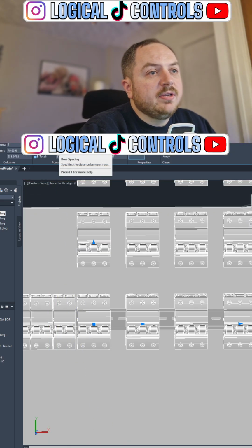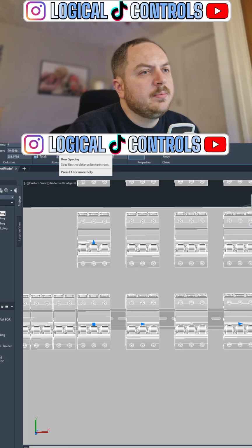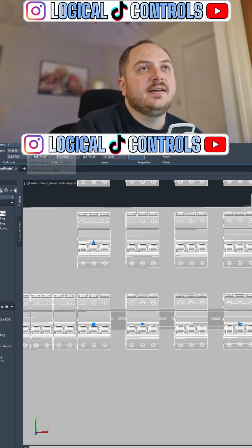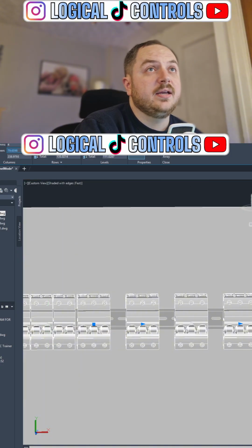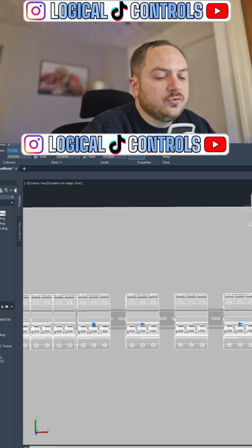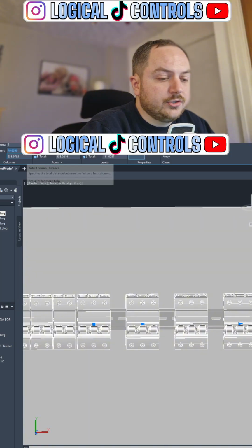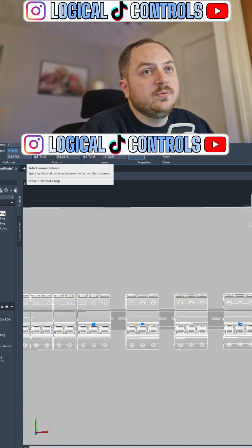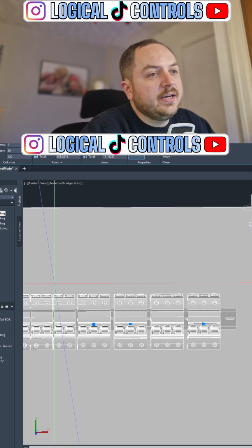I'm having to rebuild an unlabeled panel with 10-year outdated drawings, made of cables loose. Yeah, it gets like that, doesn't it? Retrofitting panels can be a nightmare, a real nightmare. Especially if the drawings are old and out of date, you're having to guess stuff. Well, the only real thing you can do is just go and do a site visit and just start tracing wires out and stuff like that. Yeah, it's never easy, but that's why you get paid the big bucks.